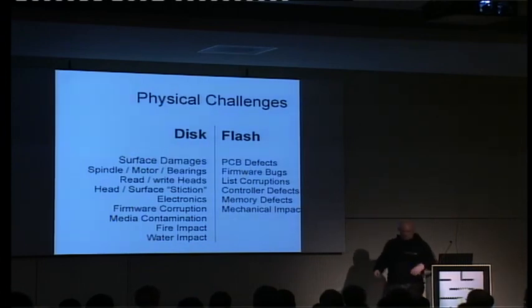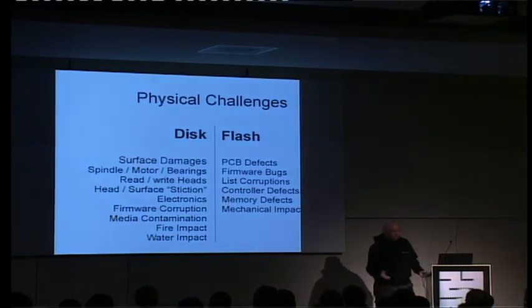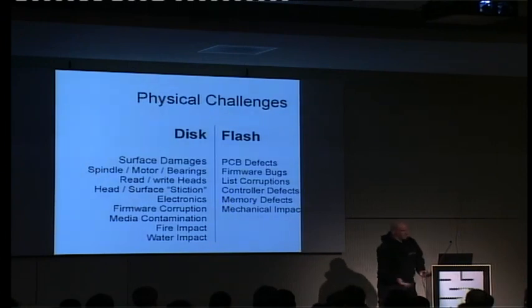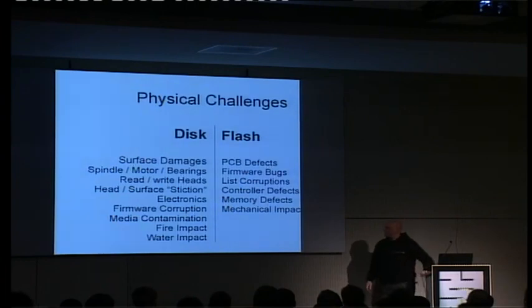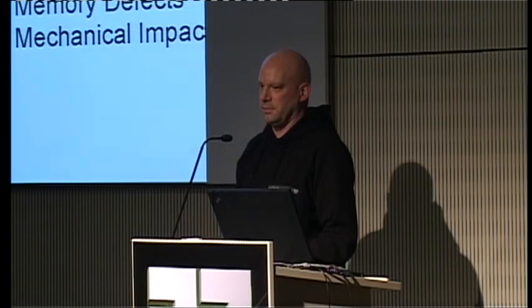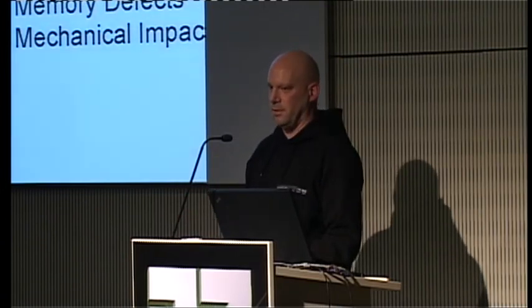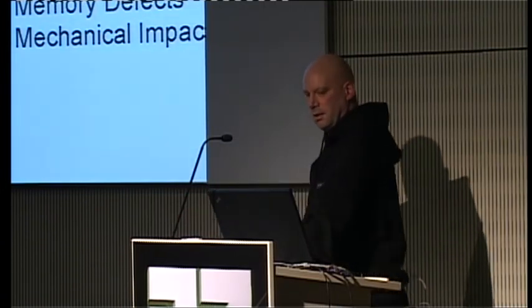But if you move a drive and knock it against something, then the heads could either fall off the parking ramp or fall out of the parking zone, and then they will, in most cases, immediately be stuck to the surface from adhesive force, and you won't get them off live.